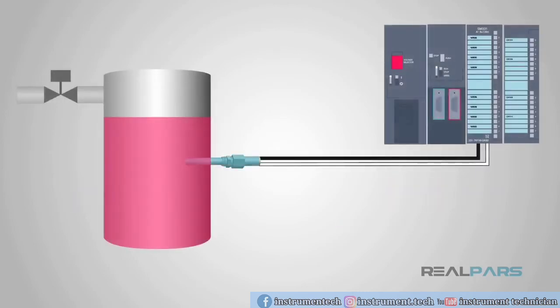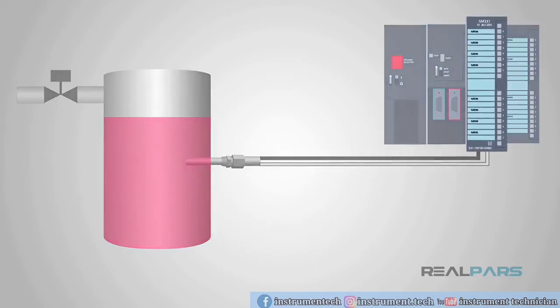The older type of temperature device is a thermocouple. This type of device generates a small signal in the millivolt range, depending on the temperature at the junction, the point where two different metals touch to create the voltage. A thermocouple measurement module is designed to process these tiny signals into temperature readings, and they have several somewhat picky features.